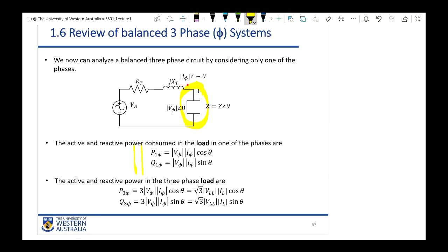Okay, by using a formula. Remember we mentioned a moment ago that the complete power, S, is equal to V by I conjugate, right? This is what we mentioned. But how to derive the real power and the reactive power from this complete power? You must remember that you mentioned in last week, which is called power triangle.